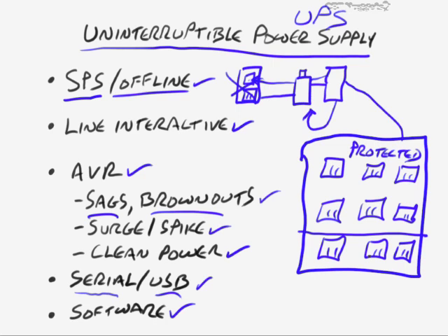And they have software such that when the power does go off, a signal is sent from the UPS to this computer over the USB cable, and it interacts with the software that says, hey, power's gone out. The software also can identify how many minutes of uptime I'm good for on the battery here. So let's say that it says I've got 20 minutes. Well, I can configure this software so that it says, hey, after 5 minutes, go ahead and save my documents.